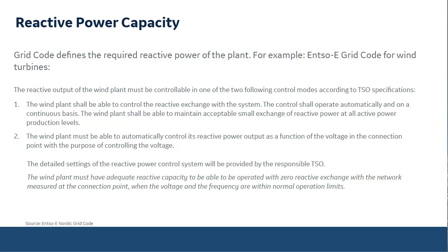You have to have some kind of reactive power reserve in your network. It's mandatory. It's really the TSOs who are requiring you to do so. So you have to have some kind of capacity there. And if you can't, for example, make all the required reactive power with the wind turbines, then you need capacitors in there. So you will have the reserve that is required in there.